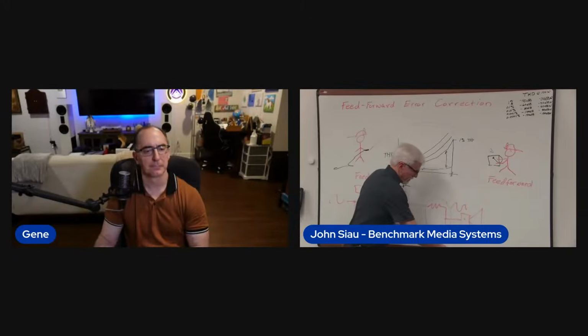Gotcha. So it's the ability to drive low impedances without an increase in distortion, and a large part of that is the feed-forward error correction. Yeah, because there are some amplifiers that don't do well under low impedances, and that's a big problem, especially at high power levels. Big problem with a lot of Class Ds, and a lot of Class Ds have quite an increase in distortion as you go up to higher power and higher frequencies. So high frequencies and high power both end up being difficult situations for a lot of power amplifiers.